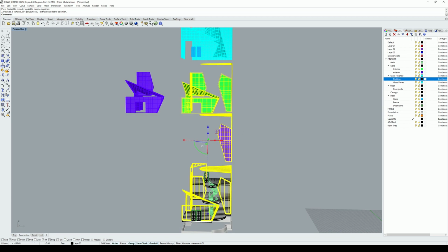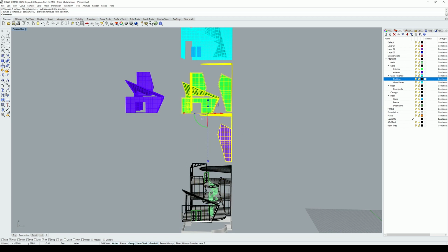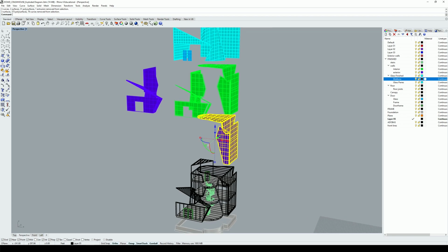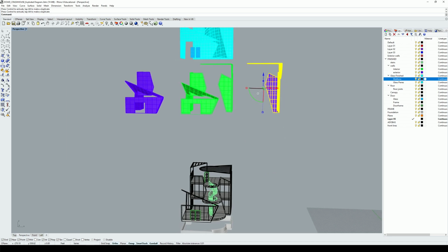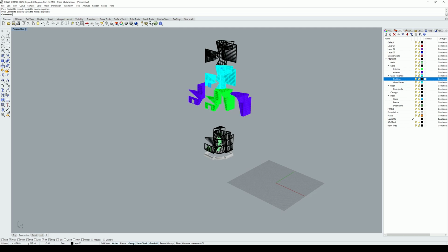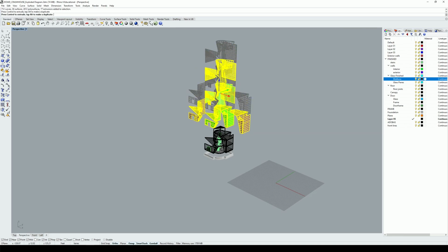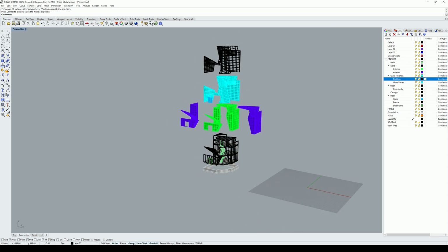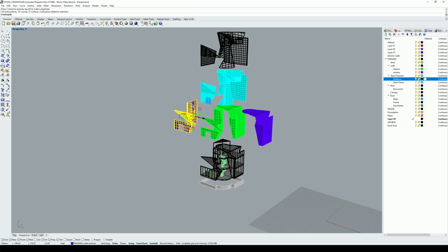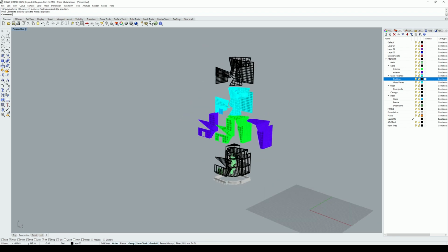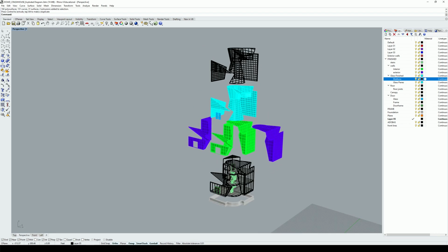Select this portion again. Group it. Pull it off to the side and up. And now I can drag all three of these guys down. And now I'm set up for my Make 2D.